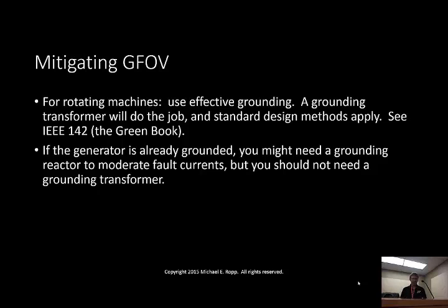Just ground the thing. If the generator is internally grounded and has a grounding transformer built into it, you might need some kind of a grounding reactor to moderate the fault currents, but you wouldn't need a separate grounding transformer in that case because it's already in there.